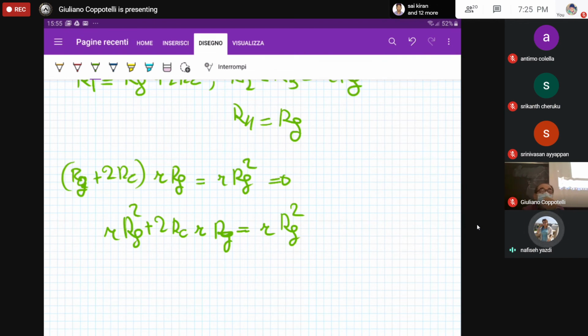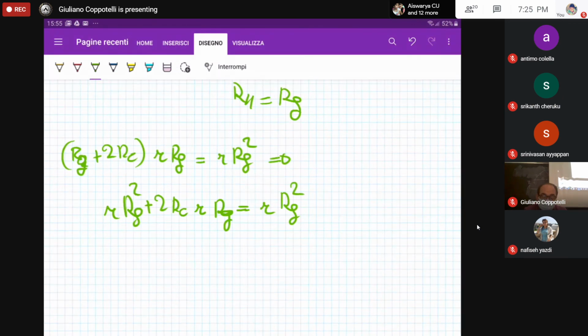That equation will be satisfied if RC is equal to 0. That's right, but RC is not 0 at all because we are having connecting cable with their own resistance that has to be considered. So that equation is telling me that it could not be solved. That is, the balancing condition is not met at all.